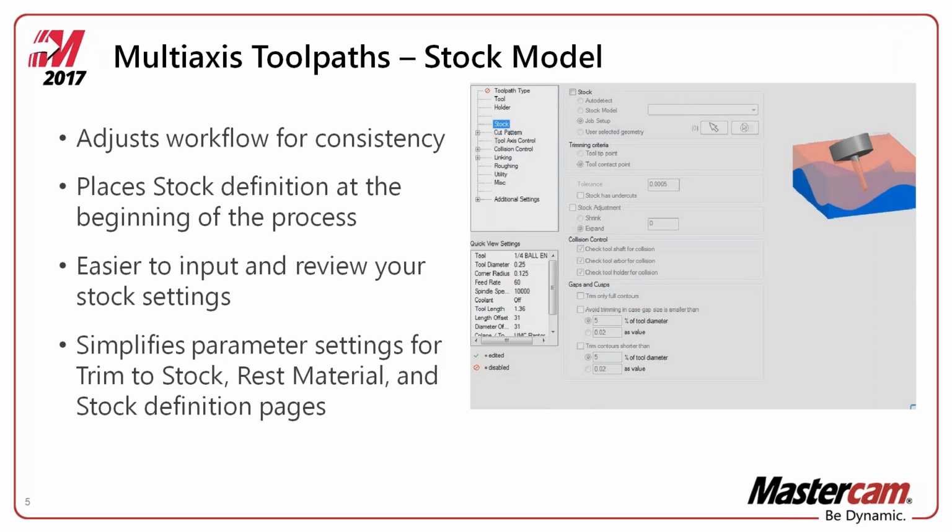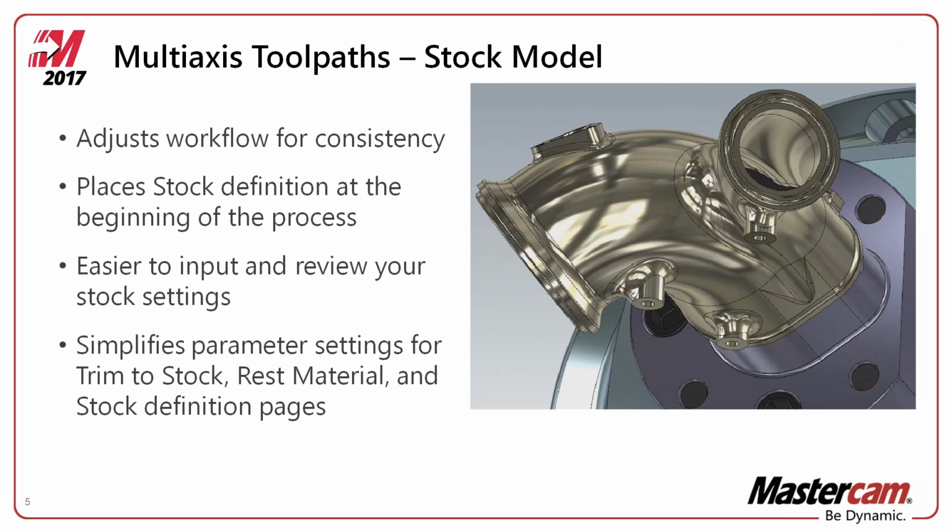Again, kind of stressing the stock model here, we have added the stock to the very top of the list for us. Before, you may have had to dig a little bit for it with a couple little plus signs that would cascade out to different menus. Because stock models are pretty important, and there's a lot of usability to them, we basically put that front and center for you to use right away. And again, we can put in stock models, use the toolpath off of that stock model, and adjust it accordingly from there.